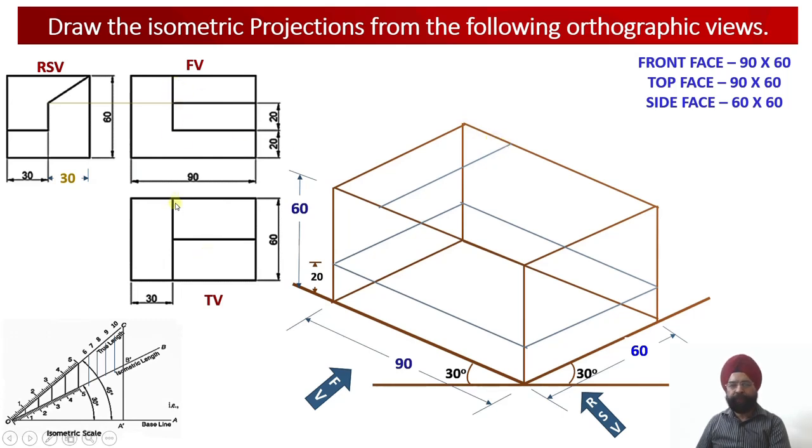So that in the top view, this top portion is a horizontal surface over there. Once I draw this projection line, which will be at a distance of 30 millimeter from the leftmost edge of this particular solid, you see, this is my left face, and from the leftmost top corner, it is this one. If I draw a projection line which is parallel to this edge, this is going to define my top face of this particular element, because this element is going to be joining with the element number 1.